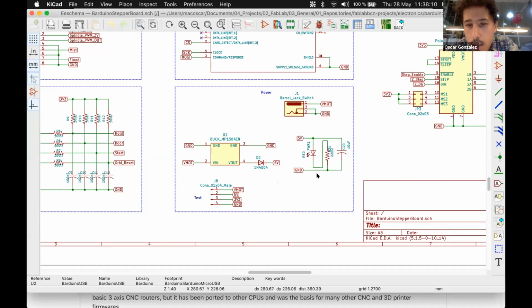There's a nice red LED so that you have some indication that the board is on. And also there's a small 28 volts. 28? Yes, maximum of 28 volts and 3 amperes. Okay, so normally we will be working at 12, but this thing accepts up to 28 volts as an input.